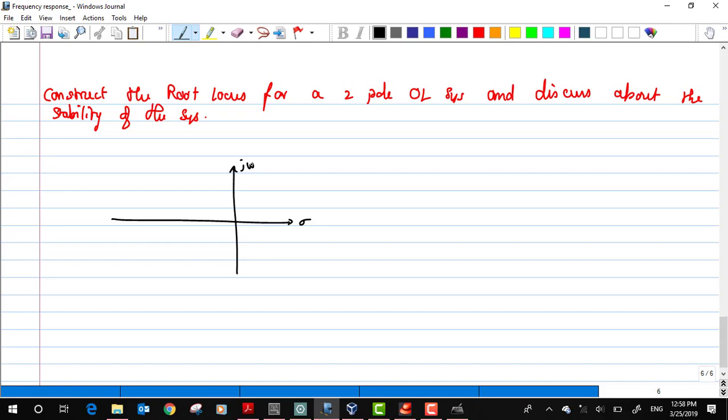Let us assume it is on the left hand side, but whether they will be on the real axis or what? Yeah, it depends is not an answer, but generally the poles will be on the real axis. If I'm somewhere wrong, you can just correct me. Those zeta values will actually matter only when you have something like a feedback. But in general, when you have a passive network like RC networks, and there is no feedback around it, they all will be on the real axis. So we assume that the system has such a thing.